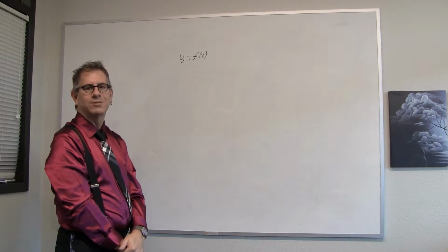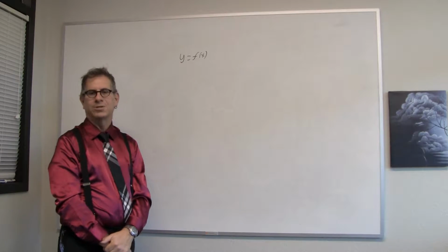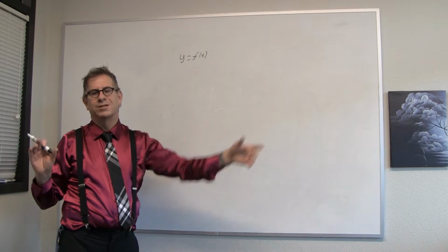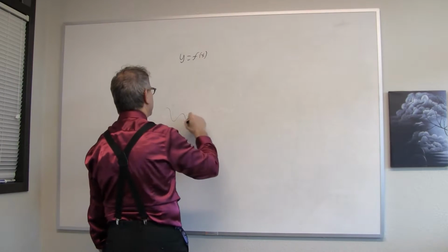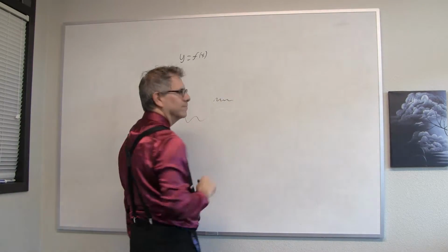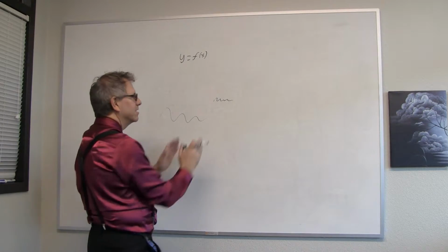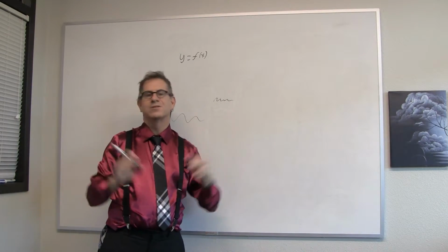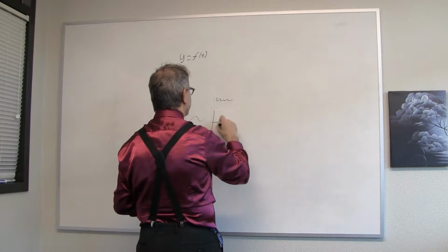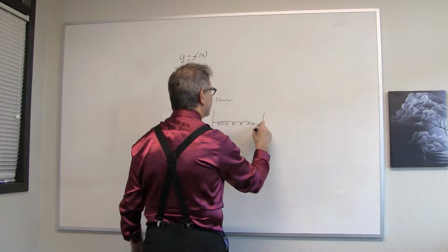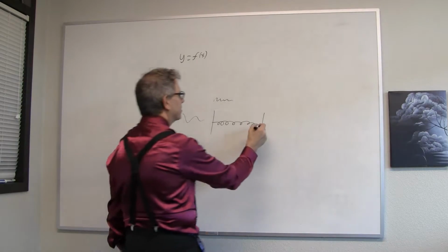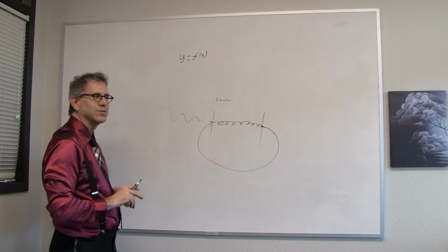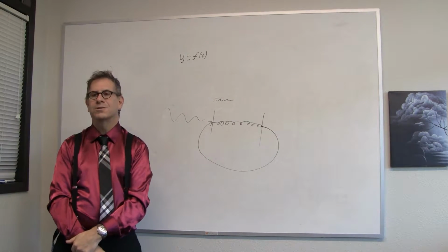Well, one way is to use a traveling wave. So an old guitar reverberation unit using a mechanical spring, transducer on one end, receiver on the other end. You put in a waveform and it vibrates this spring in a way based on this waveform, and it takes a certain period of time for those vibrations to get all the way down this spring. The units are typically like this big. And at the far end, so here's your spring, you measure the voltage, the displacement of the spring, and you use that to come back in and drive a magnet, a speaker, that will vibrate the spring accordingly.